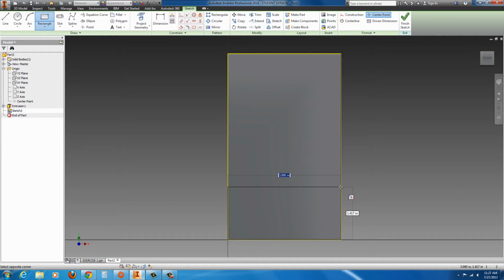Drag it up. Now you have the ability here to type in values, but we actually want to establish a relationship instead. As you know, earlier in the book, it talks about relationships, which are basically common elements of geometry like parallelism, concentricity, coincidence, tangency. You could establish those automatically by snapping to this, or you could go to the top where it says Constraints and add them. But in this case, just snap to this right edge.